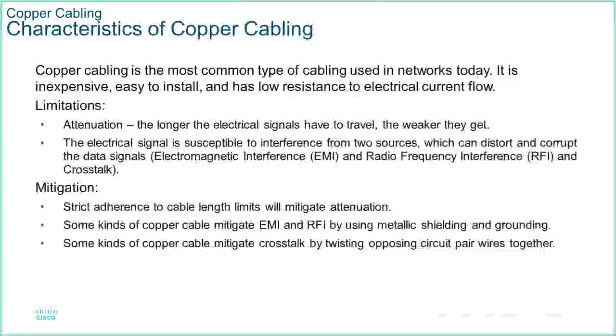All right, let's get back to this so we can get through it. The strict adherence to cable lengths: to be able to comply with the standards, we have to comply with the cable limitations that they put in, and that's all to do with signal strength and the integrity of the signal and the encoding.